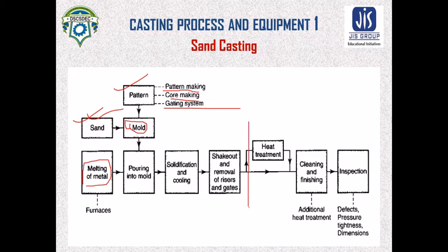Then here the casting process ends. But these terms, heat treatment, cleaning and finishing, additional heat treatment and inspection, are known as post processing. So this is the complete process layout of sand casting. Here it is known as post processing.